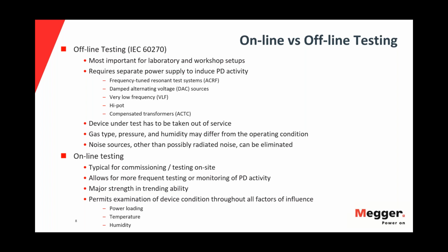The benefit of offline testing, there are a couple of benefits. First, calibration is possible, which means that based on IEC 60270, a calibrator box, a small box, applies a known value of pulse through the object, and that can be measured and calibrated for the setup. So measurement is much more accurate during offline test, to give an accurate indication as well. The noise is much less compared to online testing.